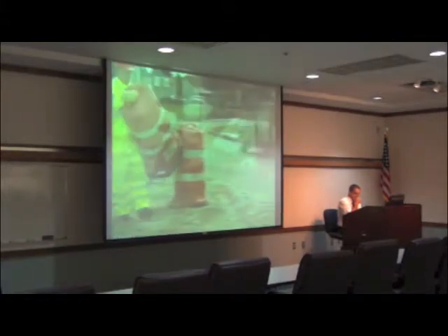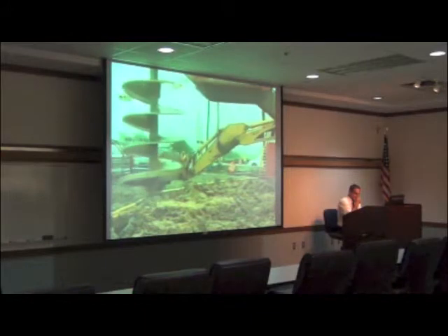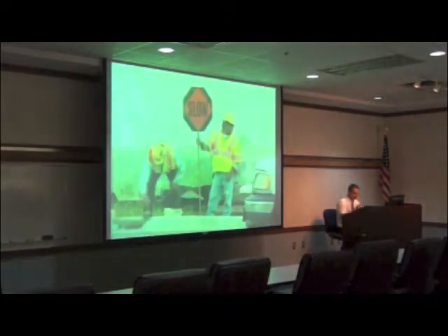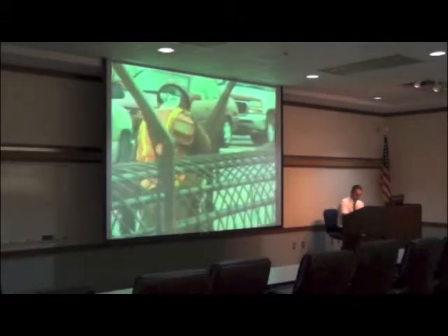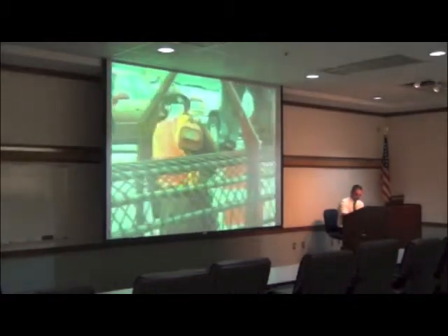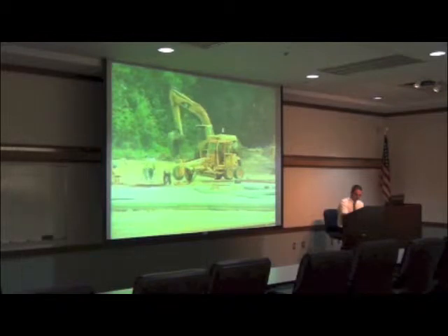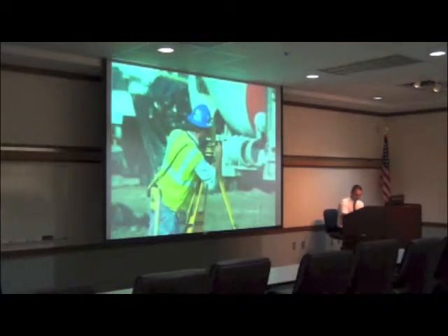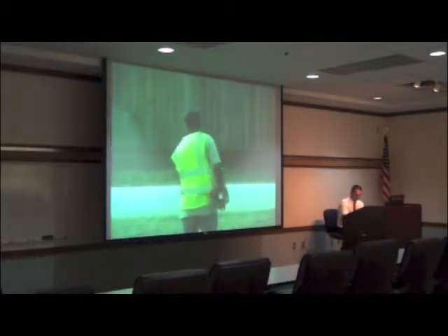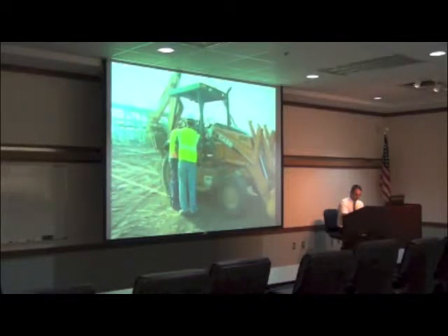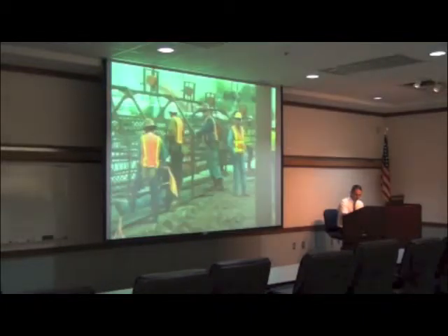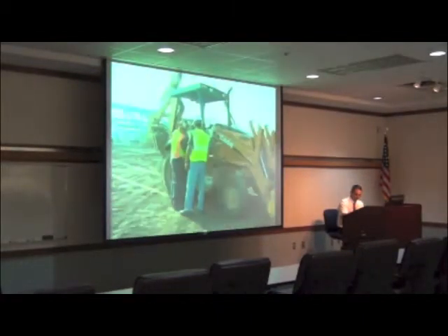Remember, when you are working in road construction zones, danger is everywhere. Wear high visibility clothing appropriate for your job. To help ensure safety, you may want to consider wearing high visibility clothing when you anticipate contact with moving equipment. For example, during interior demolition work, site work, or landscaping operations. High visibility clothing is specifically designed to help reduce risk in construction zones. Wear it and be safe.